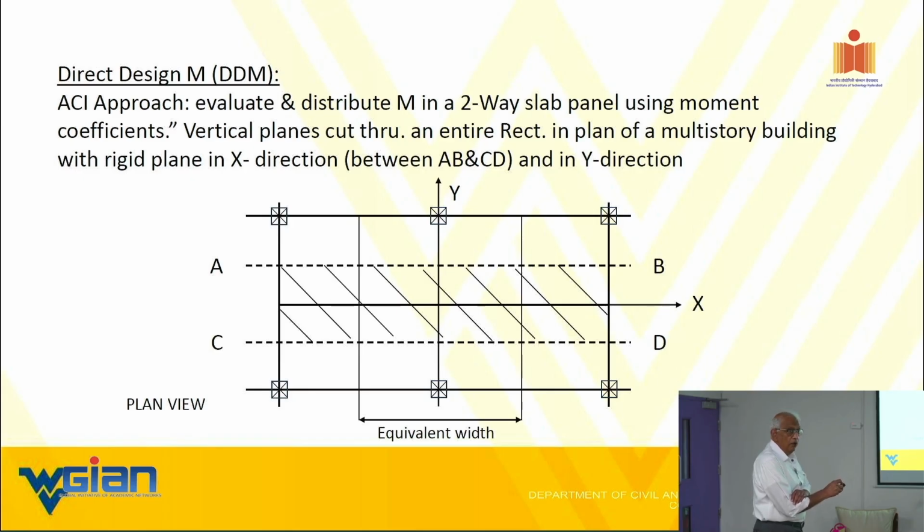But a point will come, this is what is called redistribution. A point will come, that crack will not go here. It will go there, that crack will go here, like that. That is called yield line theory. Post-cracking phenomenon is what you see.